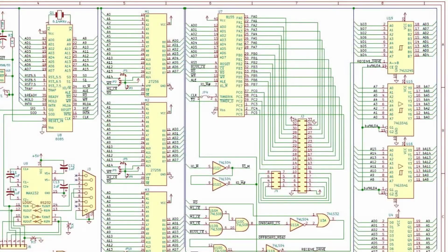So if we look at that glue logic, these inputs are the onboard selects for the 4 memory blocks decoded as onboard memory. If any of these are asserted during the read strobe, the data bus contents are placed onto the STD bus. So that means it's an onboard read. In addition to that data going into the processor, that data is also put out onto the STD bus. But during the read of an offboard memory, the transceiver drives data from the STD bus onto the local processor AD bus, so that the 8085 can read whatever is out on the STD bus.